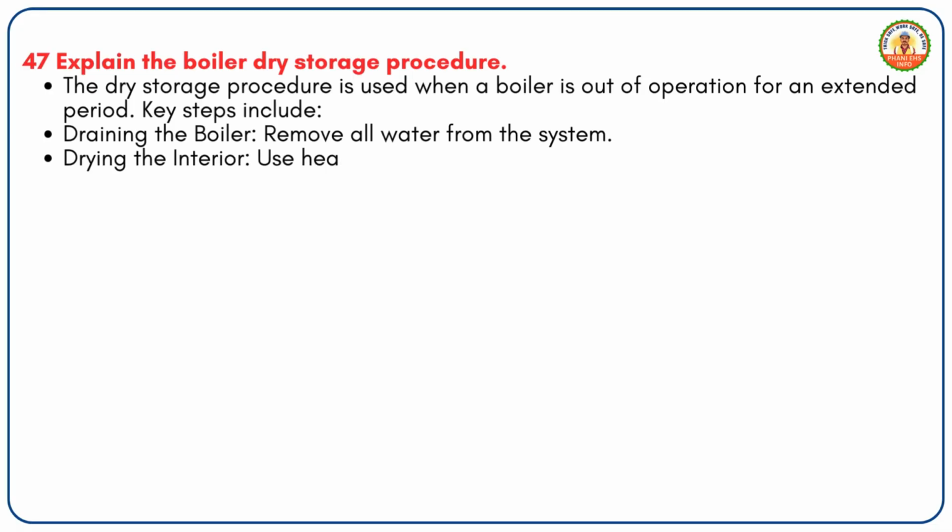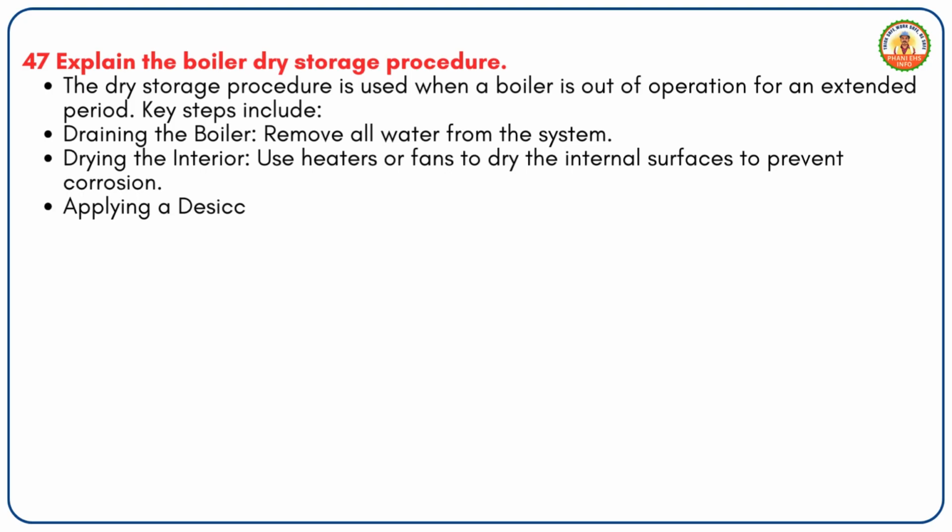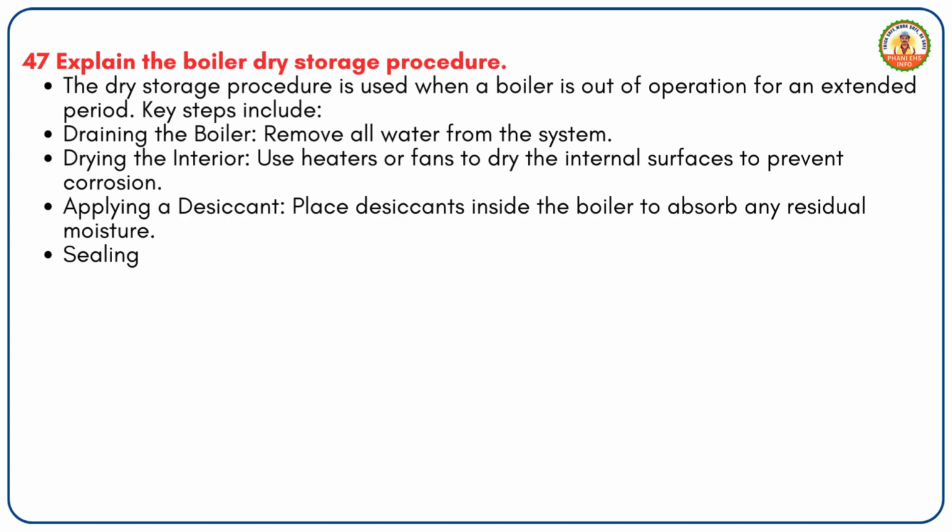Drying the interior: use heaters or fans to dry the internal surfaces to prevent corrosion. Applying a desiccant: place desiccants inside the boiler to absorb any residual moisture. Sealing the boiler: close all openings to prevent air ingress.